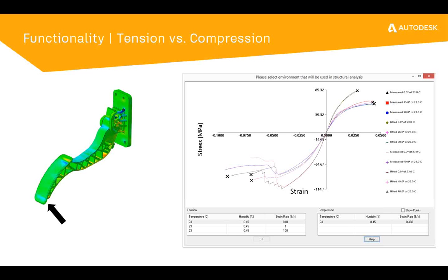But if all we have is 0 and 90 degrees, we see this a lot from material suppliers and test labs, where they test at 0 and 90, but the 45 data might not be tested for. And so what the Helius PFA software requires is the 0 and 90, and it will assume a 45-degree behavior if not supplied. But the best practice is, if the 45-degree test data is available, let's go ahead and use it.